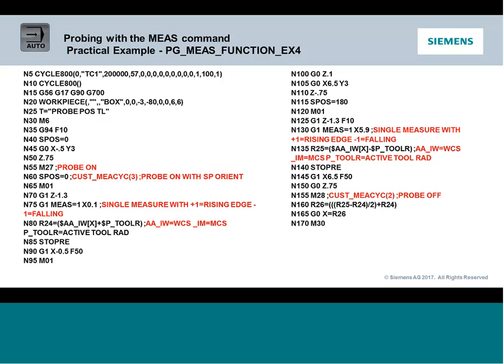Or you might have to trigger our custom edge cycle. That's another way to turn things on. So this is certainly an area where you have to play around with how your machine is specifically set up. Then you're going to have to handle orienting of the probe. Generally, whenever you're taking measurements, especially if you're bouncing around different features, you're going to want to make sure you're touching the same point of the probe each time. So you're going to want to position.